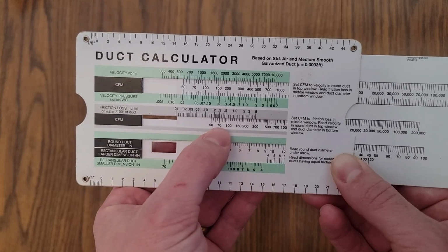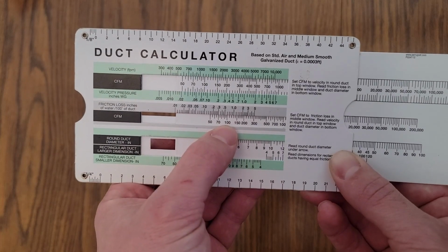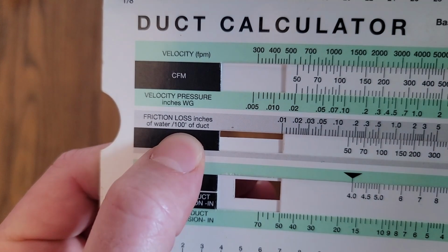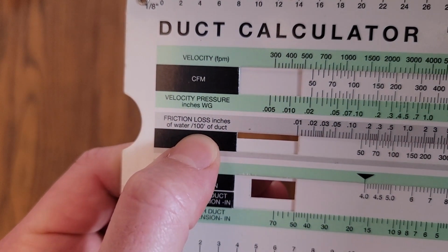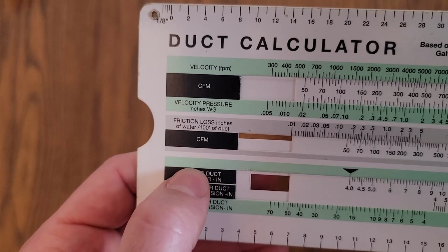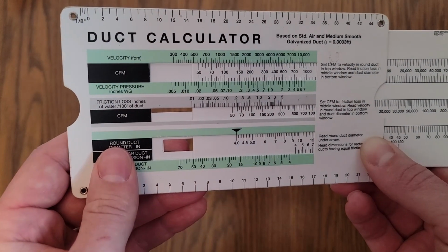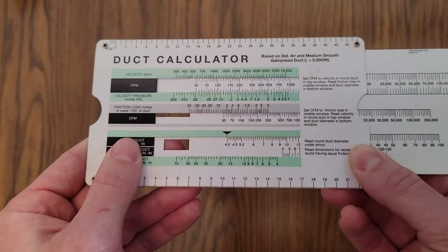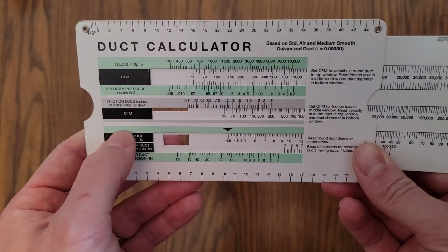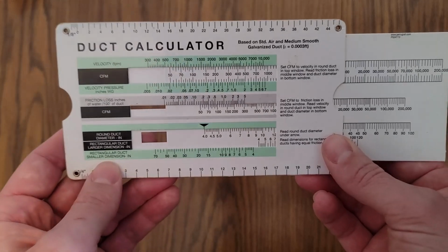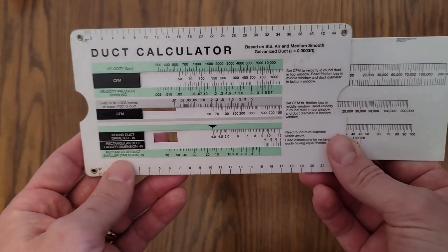We're going to use this relationship for 4-inch round pipe, 0.6 over 100 feet, because over here it's friction loss per 100 feet. We're going to use this relationship to determine the amount of static pressure from the piping that makes up our system. So we need to figure out how much friction loss we have. That'll help us size the radon fan.